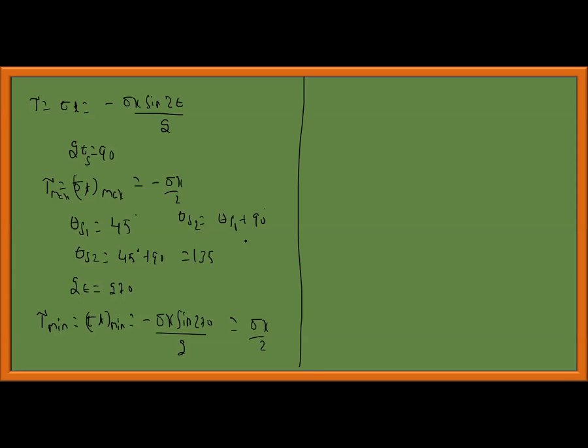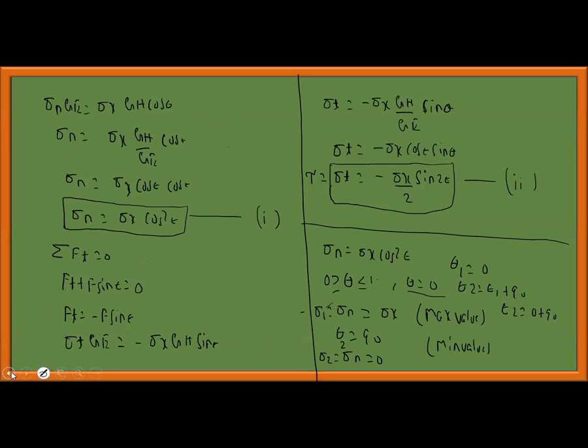It means my shear planes are mutually perpendicular to each other. Theta s2 will be 90 degrees to theta s1. Similarly, principal stresses are mutually perpendicular. If theta 1 is at some angle, 10 degrees, theta 2 will be at 100 degrees. That you should understand.